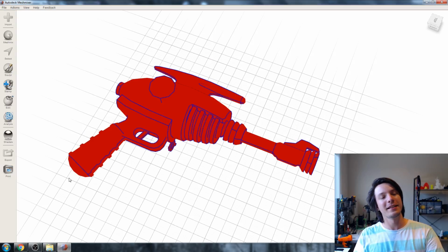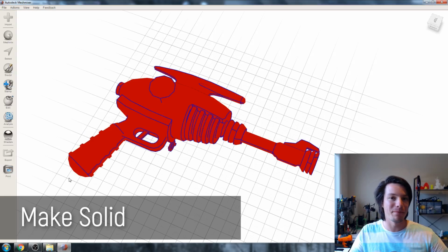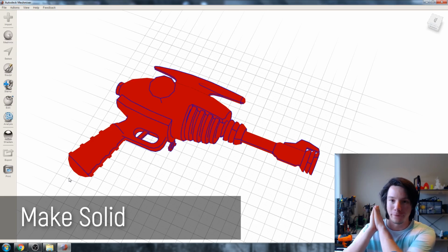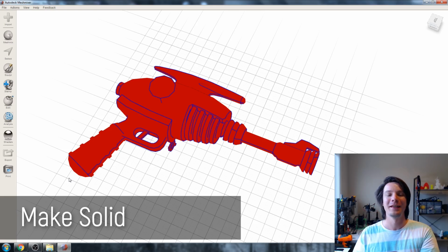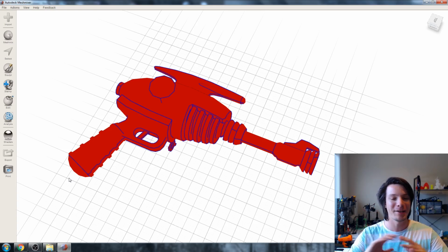Okay guys, the last tool we're going to talk about in this video is Make Solid. It's a tool you're either going to love and it's going to get you out of a bind, or it's just going to frustrate you. Make Solid will take an arrangement of bad surfaces, non-uniform, non-manifold surfaces, and try to make them solid, manifold, watertight. In the industry, it's known as shrink wrapping.